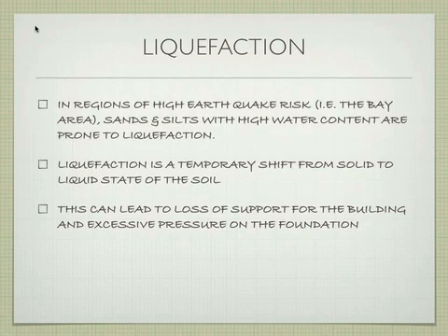Same thing with Treasure Island. As you go across the Bay Bridge, that little flat island down there, same concept. They filled. Because they put all this fill in, it's not the most dense, great soil to build on in the first place, but it has a very high water table. If you've ever been out there, you know that the bay is 4 or 5 feet below the top surface of those islands. So there's not a lot of distance. The water table is only 4 or 5 feet down, maybe 6 or 8 feet down on a good day from that top surface.